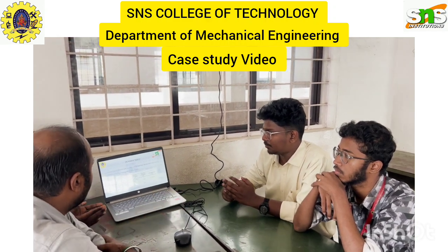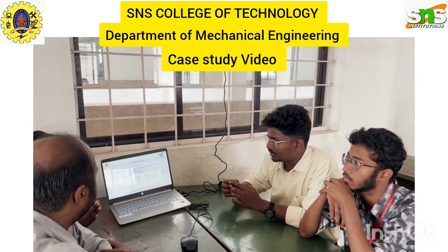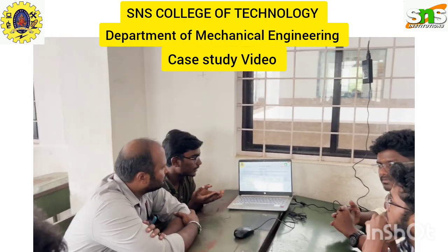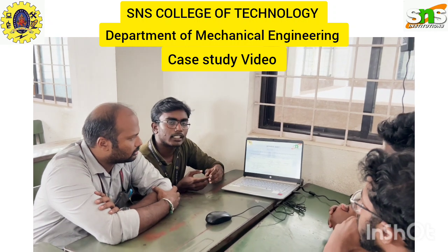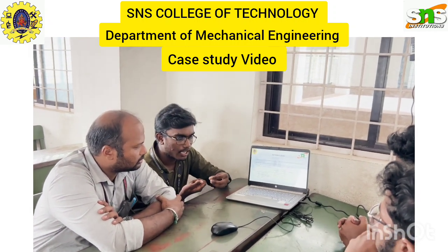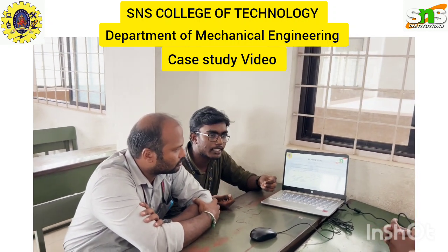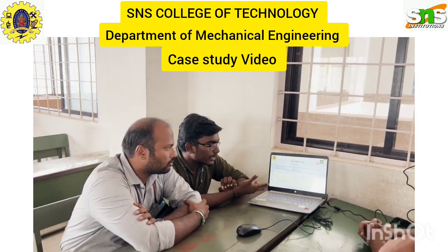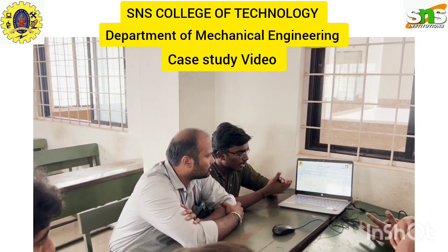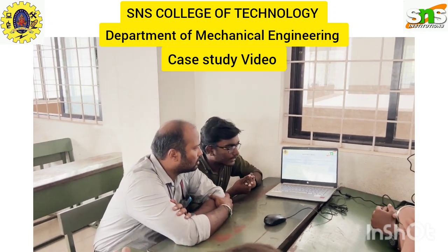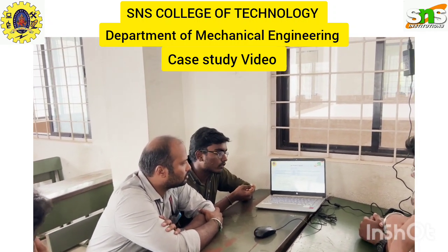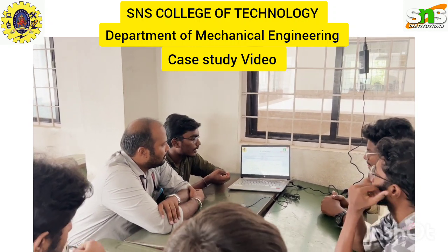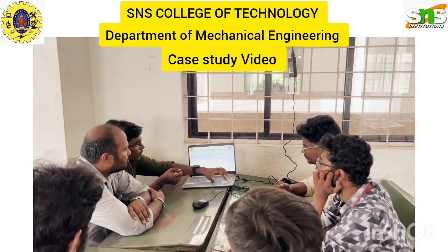Tensile testing is also mentioned here. After testing the chemical properties of the metal, we are going to check the tensile character of the metal. Tensile refers to elongation; it is about checking the elongation limit and elastic limit of the metal. The yield strength was recorded as 101, the tensile strength as 140, and the elongation as 19%. The elongation of the metal looks good.